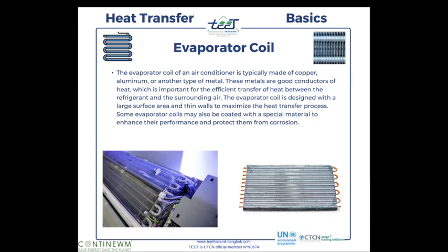They could use continuum? So a heat pump, I mean, an air conditioning is a heat pump. They are just two different words for the same thing. Heat pump is really a process word. Let's say you pump the heat. When you use air conditioning, you pump the heat from inside and take it out to the outside of your room, right? That's why you have cold air in the air conditioning. And if you go to the compressor, you have hot air because you pump the heat from inside to outside.